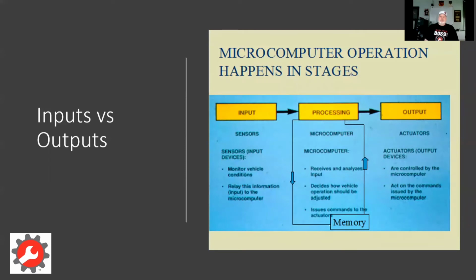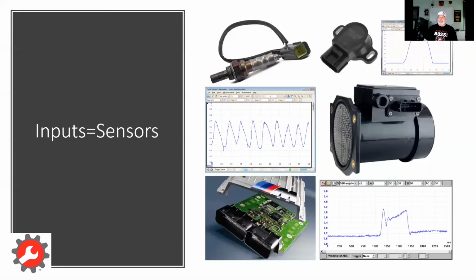So find the connector, get it connected, boot up the scan tool, and take a look at it. From there, what you need to understand is that your processor, your ECU, is exactly that. It is a component that takes inputs and creates output signals. That's all it's doing. So once you understand that, we have grounds, we have power, we have inputs, and we have outputs. Helps you kind of understand, hopefully, a little bit better about what's taking place.